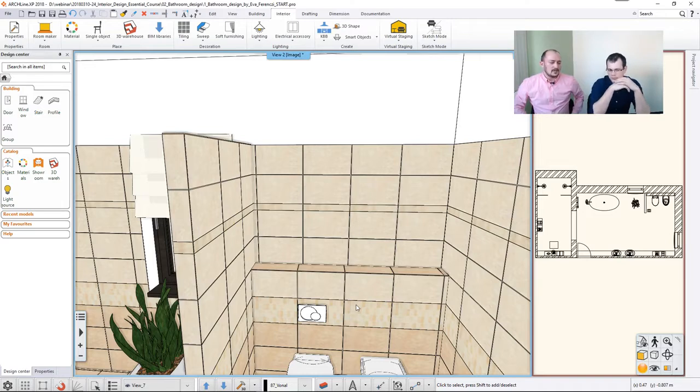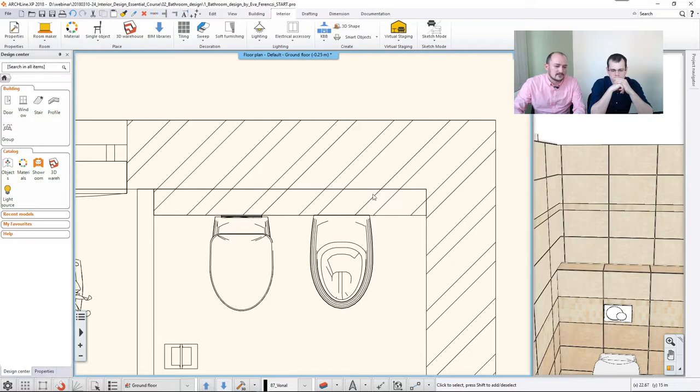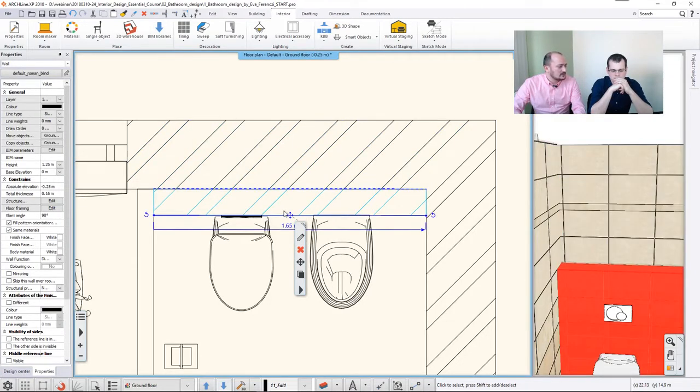So yes. Because of how this project was modeled, it was actually modeled in a very simple way. Let me just reveal this trick. It was actually one wall and another in front of that. So when you tell the software to cover a surface of a wall, it won't consider unconnected walls. These are not connected into each other. So now they actually behave like two totally separate walls. So the software covers one and the other. Either you can solve this by making them connected or model it somehow else. Or if this is the easiest choice, then you can still make changes on this wall.